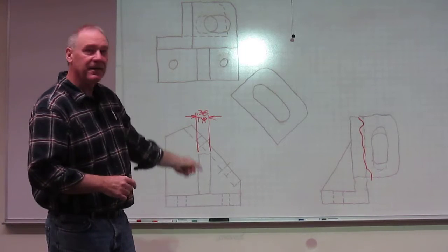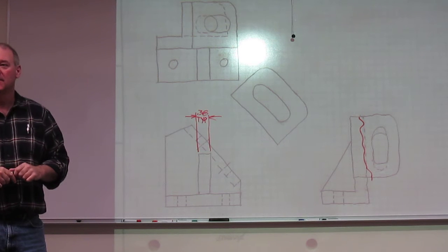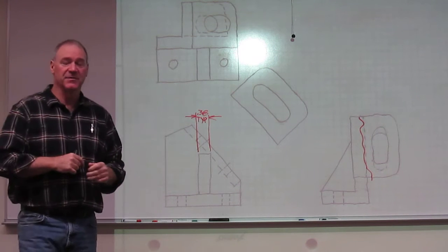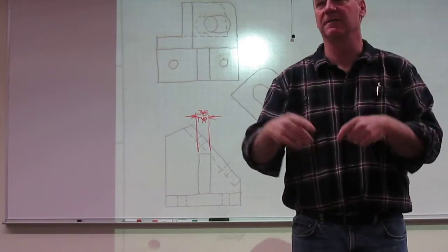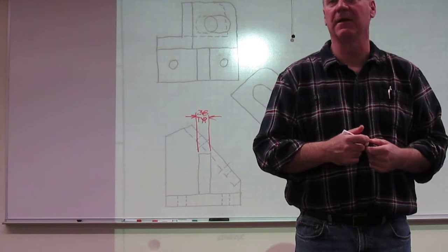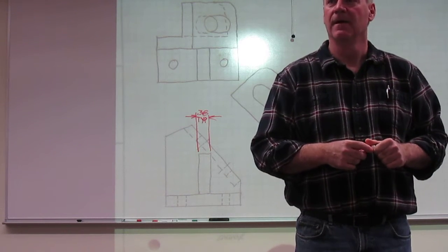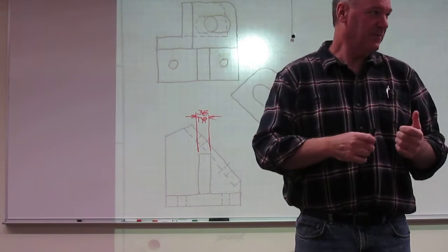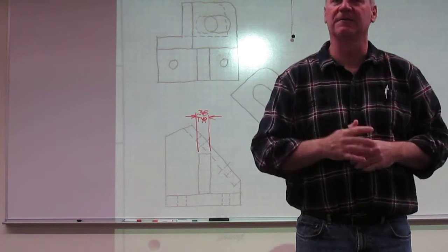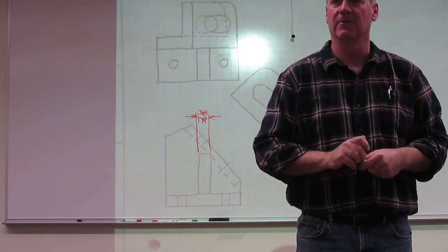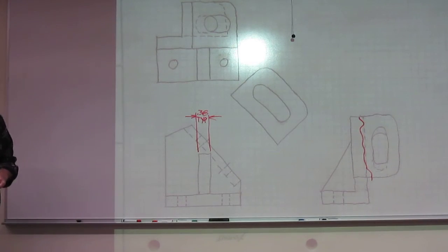So now, whenever they see a plate, and I have to make sure I leave it undimensioned in all other views, then it should be 0.38. I do have another option. Can I put it in my general notes, saying all plates constructed from 3/8 material, and then not dimension any of them? Yeah, I can do something like that too. The thing is, here we've got a difficult situation and we can't do it really with pictures. So we want to make sure we're joining our text with it, as long as it is clear. We want to try and clarify that as much as possible. So that's an instance I would do with that.